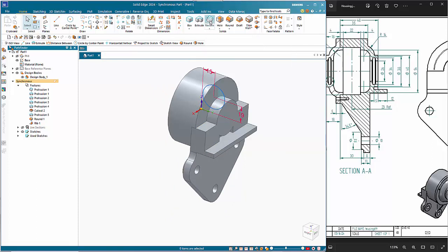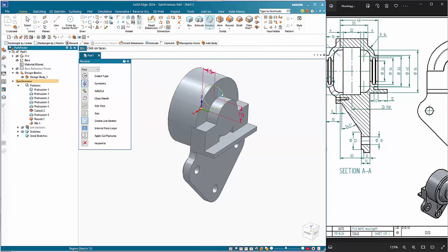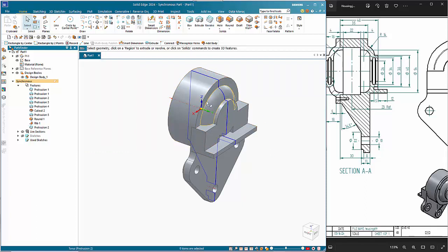What we're going to do is a revolve. It's all solid inside, so we're not too worried about that. You want to check on single or chain, doesn't really matter. Select it. That brings up the steering wheel. I'm going to go to a finite extent, grab on the control knob and click down on the axis, and then from here you want to go to the torus. Make sure that you've got symmetric on, and you want to come around 180 degrees to get that in place. So with any rotational features, that creates a live section.